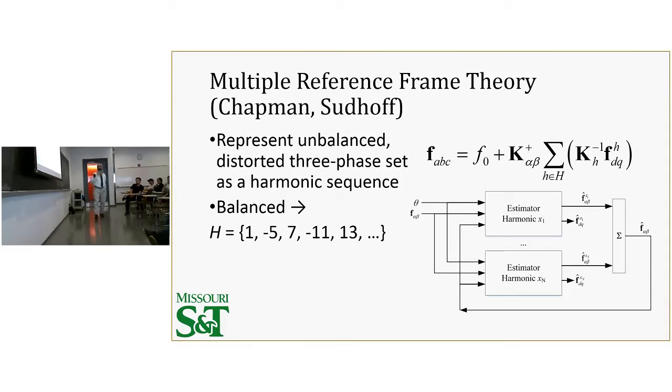So here's the multiple reference frame theory, and this goes back to Pat Krause's work with Sudhoff. Pat was a professor here when I was getting my PhD, and this came up in the context of machine control, motor control, and that is we can represent an unbalanced and/or distorted three-phase set as a harmonic sequence.